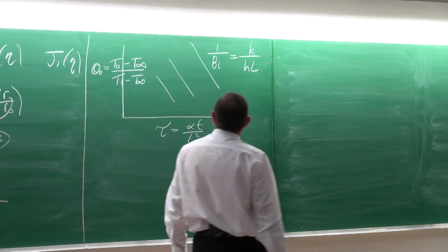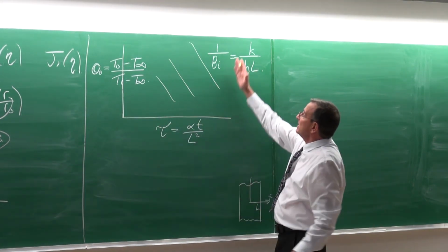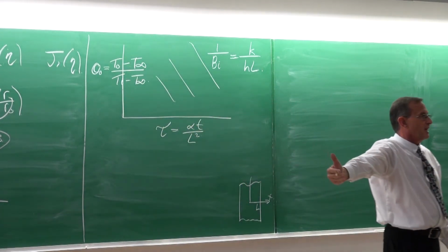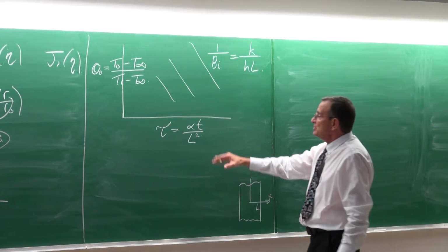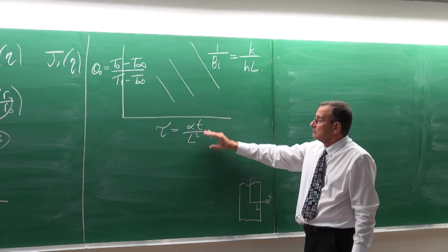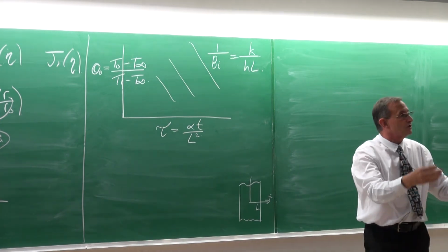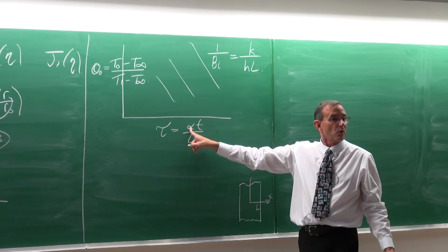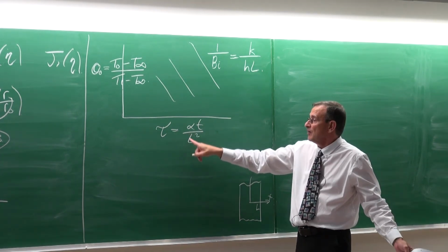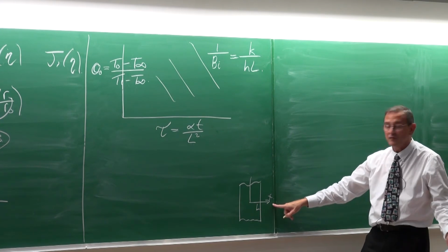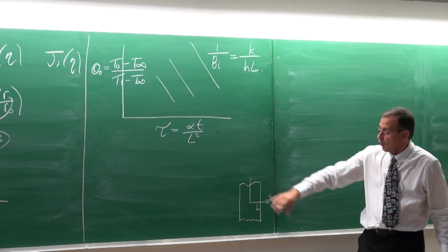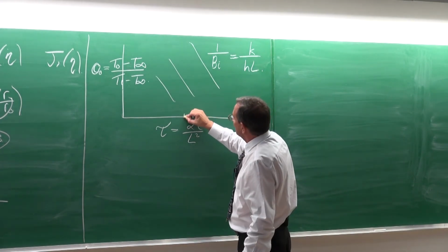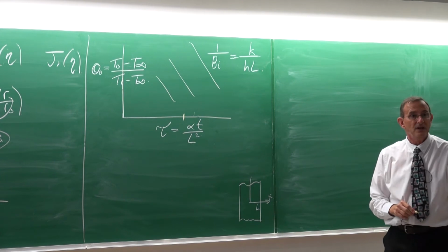Okay. Right. So there are always 3 variables. You need 2 to solve the other one. Suppose the time is given, so we want the solution after 1 minute. Then you can calculate this. You'll obviously have the properties of the material, so you've got alpha, and L is the dimension of the large plane wall, the thickness, or the half thickness. So you can calculate that. Do you agree? Okay, so let's suppose that is the value there.